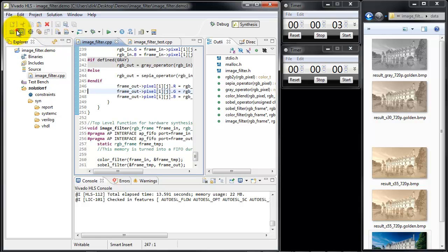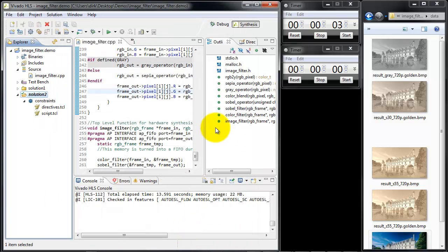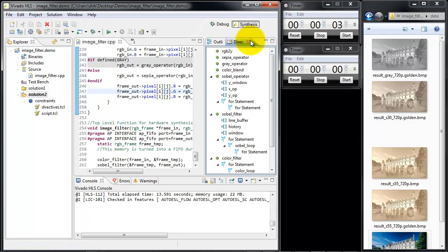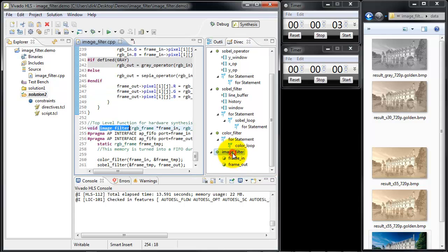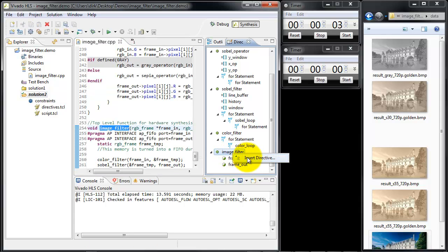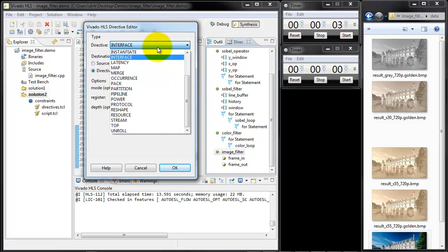We simply copy any and all constraints from our first solution. For this second solution, we would like to introduce some process parallelism by having the two filters of the design run in parallel. Vivado HLS makes this easy for us as it extracts the optimizable objects from a C specification. These are basically the functions, loops, and arrays. The top-level function calls the two filter functions.